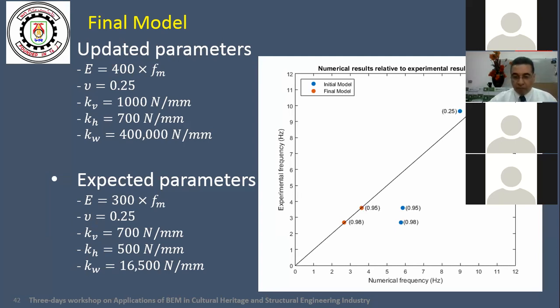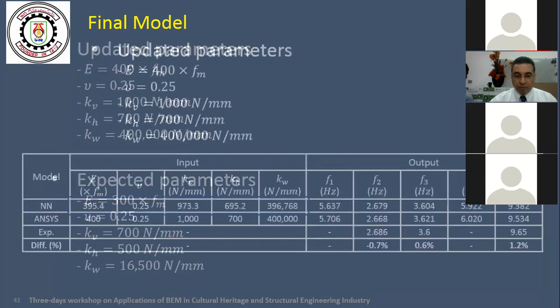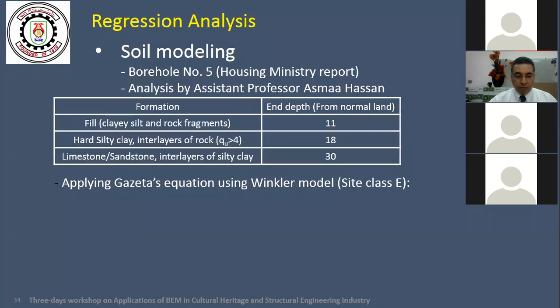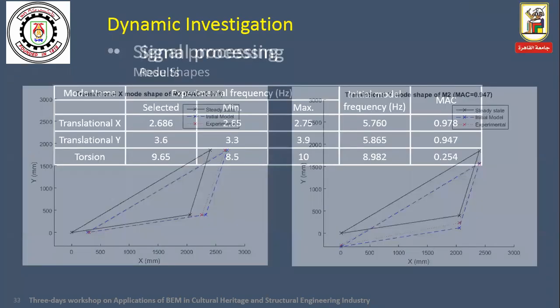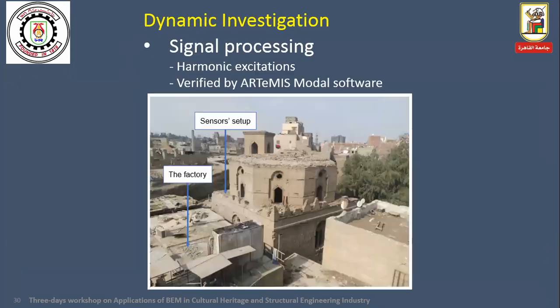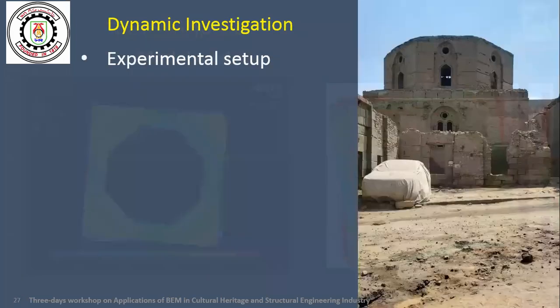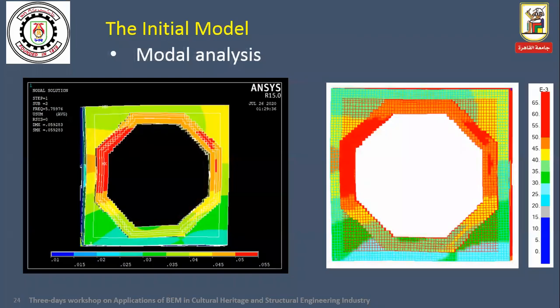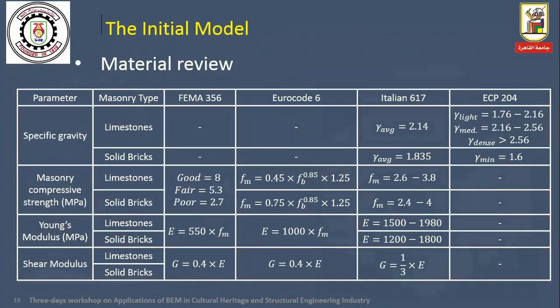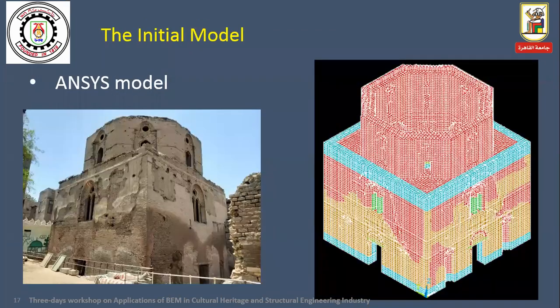You made the solid model, the contact between the solid blocks. Was it adhesive material or was it just fixed between the two blocks? Because I think that there is going to be totally different values for the model analysis if we change the contact surface properties, especially that in Abaqus we can do this, maybe not in ANSYS. But if we change this contact between the two blocks, or how it is performed in this model, was it totally fixed between both blocks?